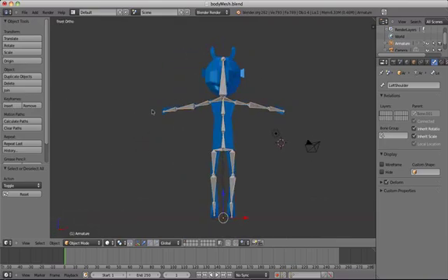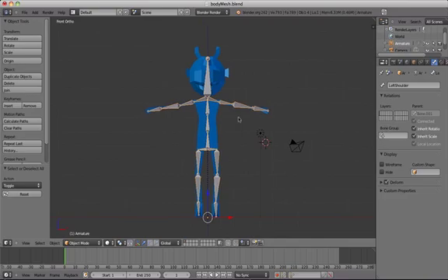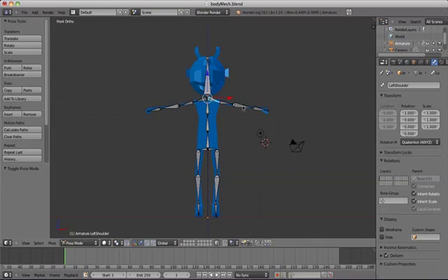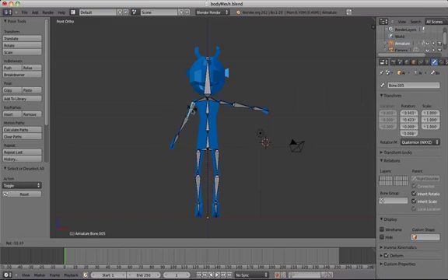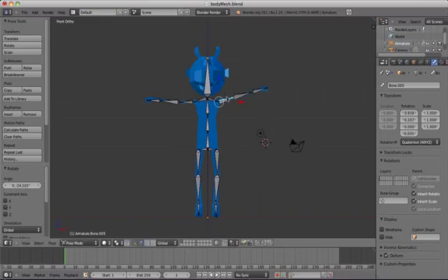Once the armature and the mesh have been linked, Blender creates a new mode called Pose Mode, which becomes unlocked. It was previously inaccessible. It's only available when you have an armature selected, which you can enter by selecting the armature and by choosing Pose Mode from the drop-down menu. Enter Pose Mode and move the bones around a bit to see how the armature works. The easiest way is if you right-click to select one of the bones and then rotate or move it and see that the mesh body follows exactly wherever the bone goes.